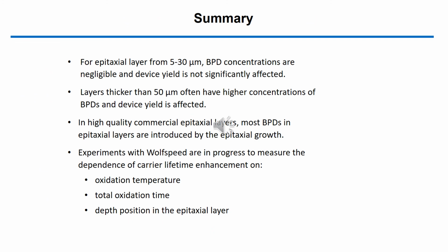In summary, for epitaxial layers that are in the 5 to 30 micron range, BPDs are no longer a significant problem for yield. However, for the thicker layers, which often have higher concentrations, device yield is still affected. We also observed that BPDs in today's epitaxial layers are primarily introduced during the epitaxial growth. We've also started experiments with Wolfspeed to measure the dependence of the carrier lifetime on oxidation temperature, total oxidation time, and depth position within the epitaxial layer.